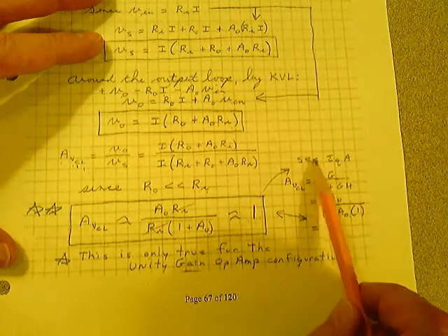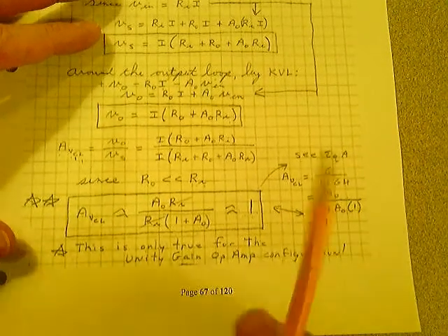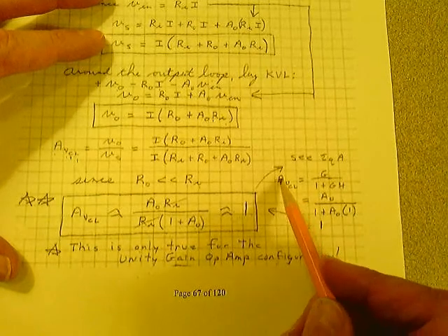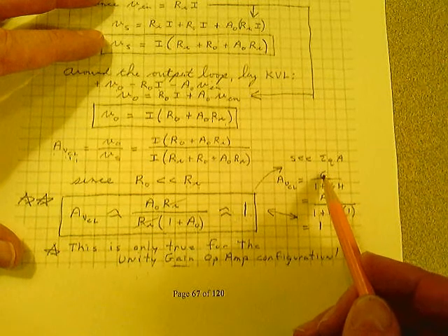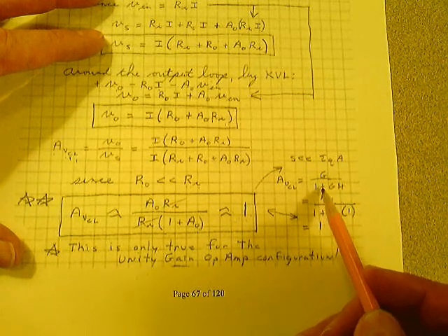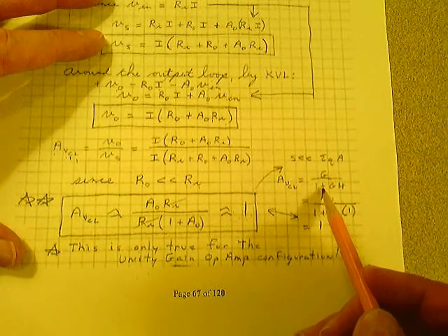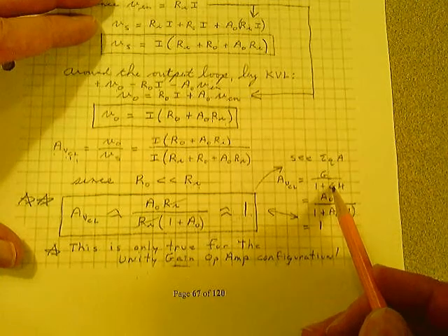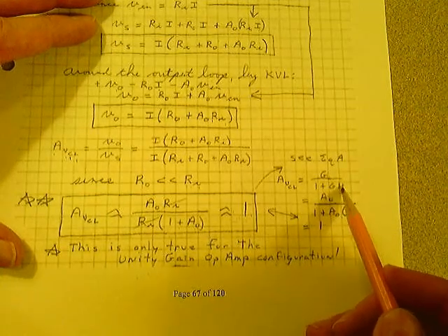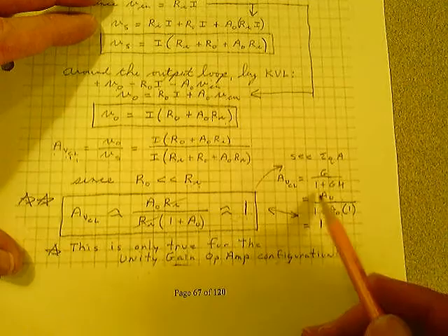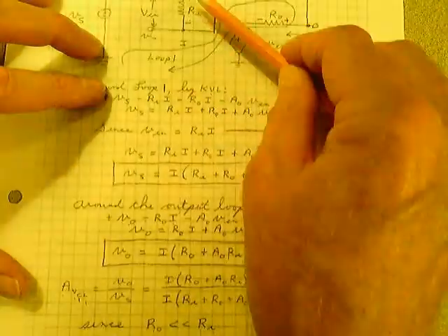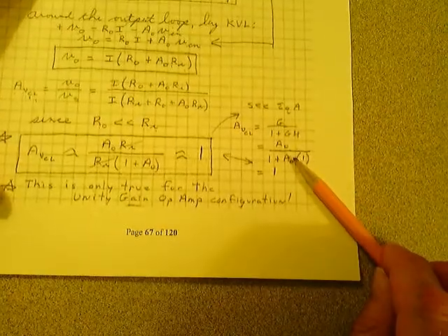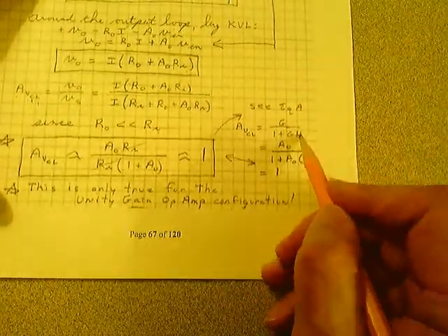And if you go back and look at equation A, remember the control theory equation I gave you, where the closed loop gain of a system is the open loop forward path gain, G, divided by 1 plus, if it's a negative feedback, 1 plus the loop gain, which is the open loop gain G times H. You plug that all in here, you get 1. Some engineers don't go through this analysis anymore. They just use this. Well, how am I getting H being 1?